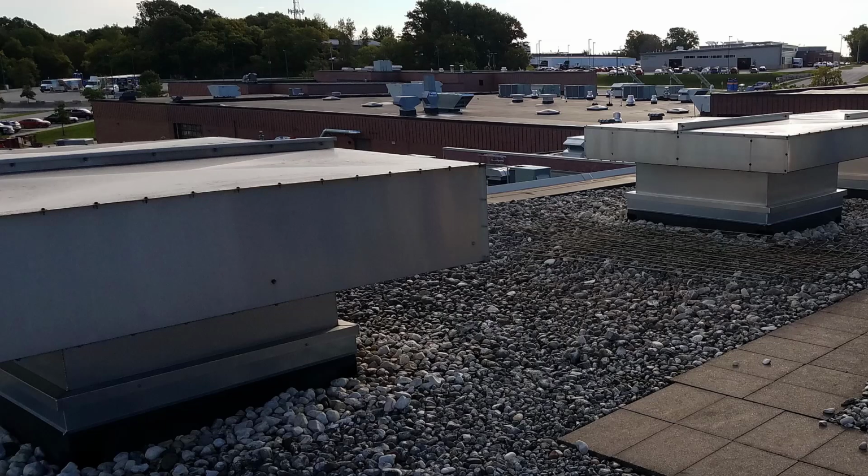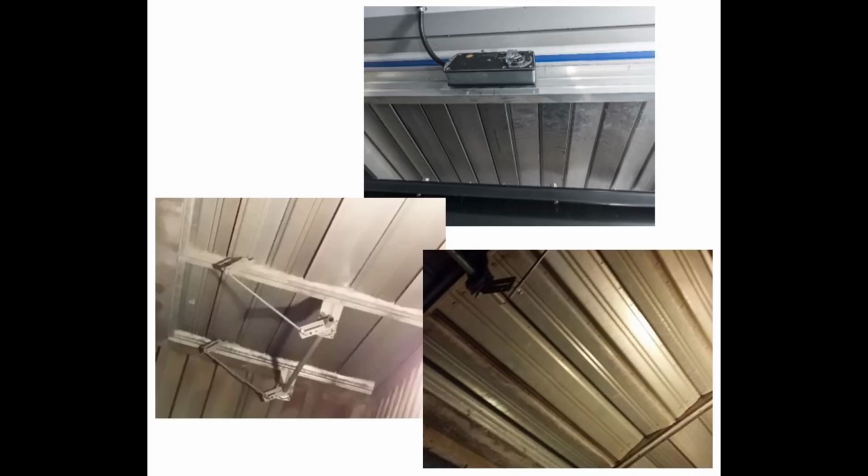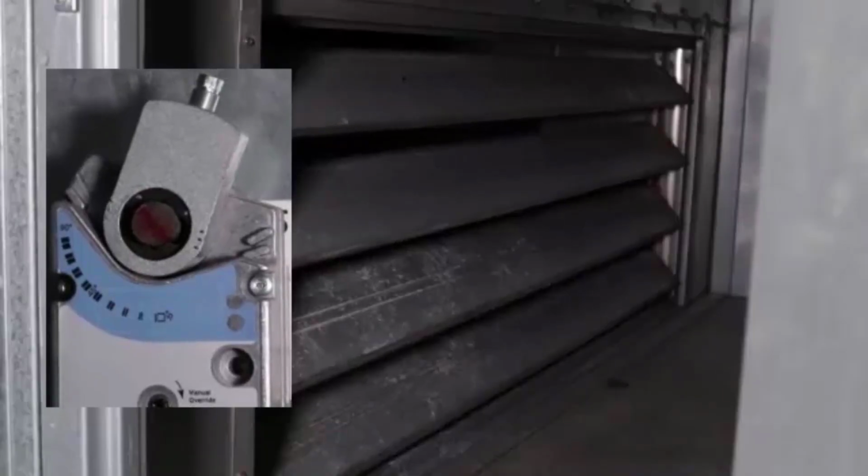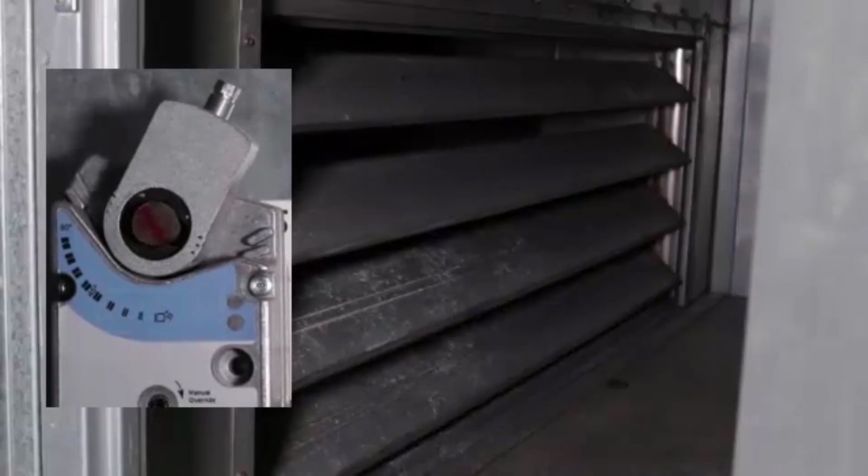Here we are on a rooftop, just above an air handling unit. You're looking at exhaust and fresh air intake vents. Each one has a hood over the top of it to keep rain and snow out of the system below. Just below the hood are adjustable louvers. These regulate the volume of air to be exhausted and brought into the building according to occupancy standards. You saw a video of louvers being opened in Chapter 1.